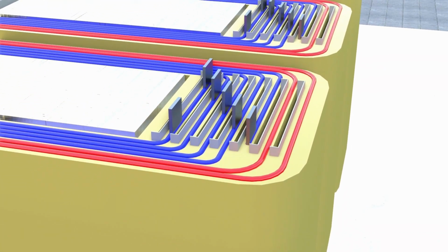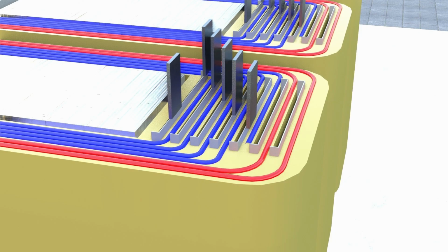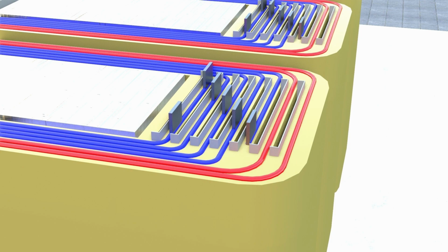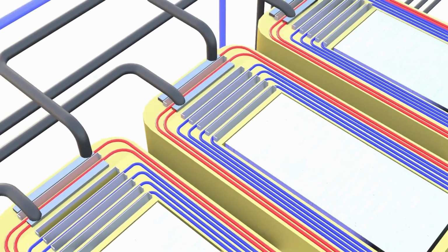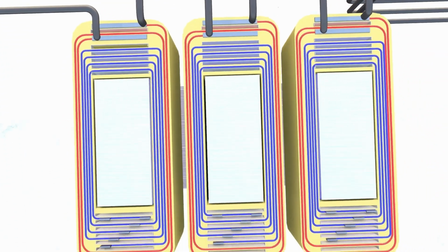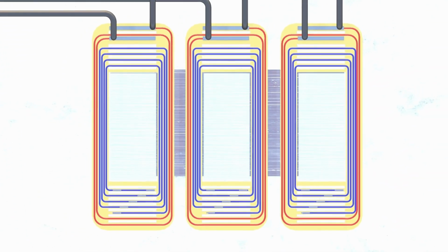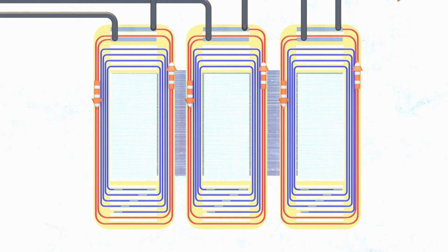The inner and outer contact is comprised of all turns, with each of the intermediate contacts only tapping a portion of the secondary winding coil. That way you can choose different translation ratios between the primary and secondary winding. Let's quickly summarize the design at this point.